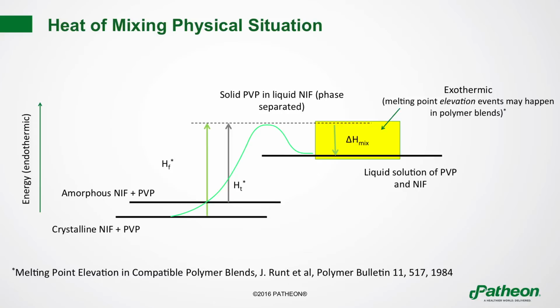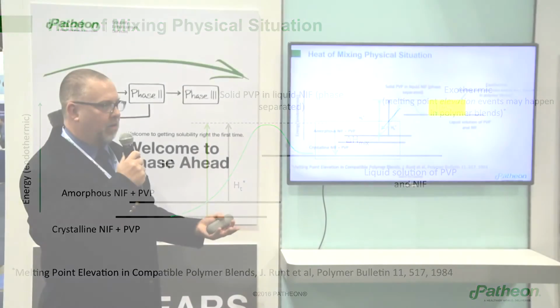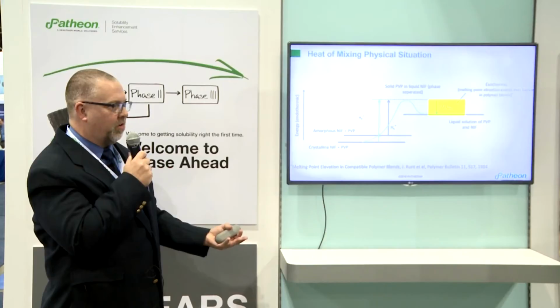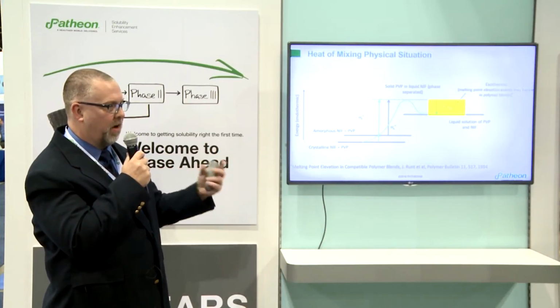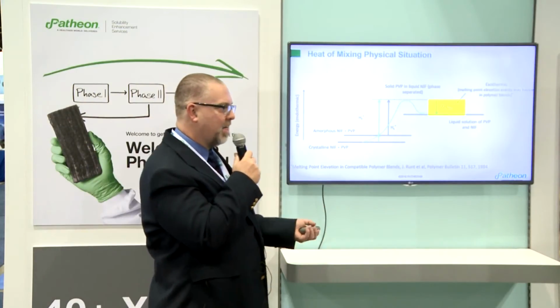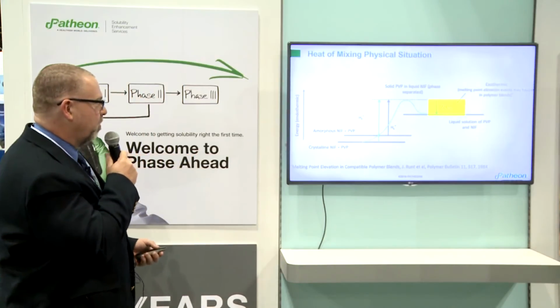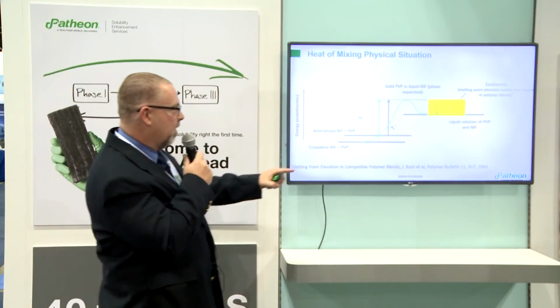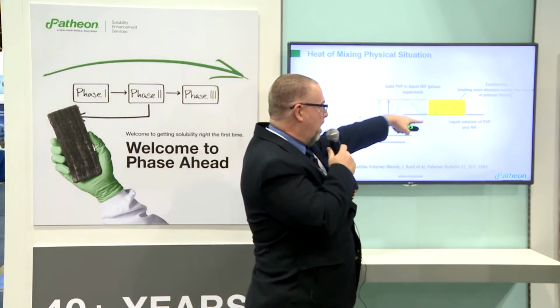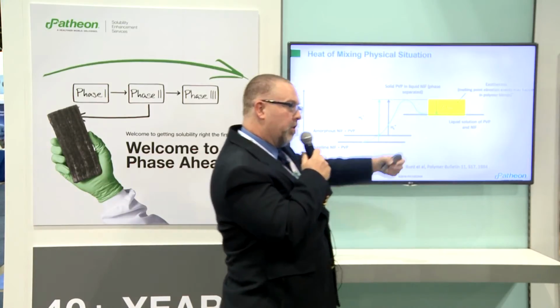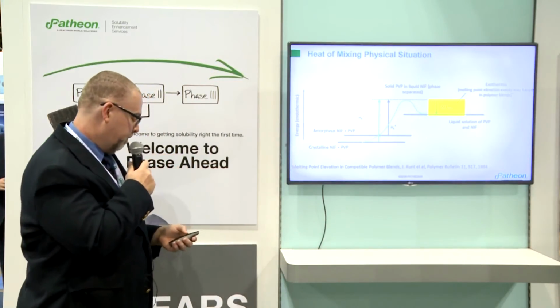These are the excess heats of mixing that you often see in liquid-liquid systems, such as ethanol and water, where if you mix them you actually get heat out of the system and the volume of the final solution decreases because it's non-ideal mixing. So we're trying to understand whether we can simulate the energy value. It turns out that we can, and do it quite well.